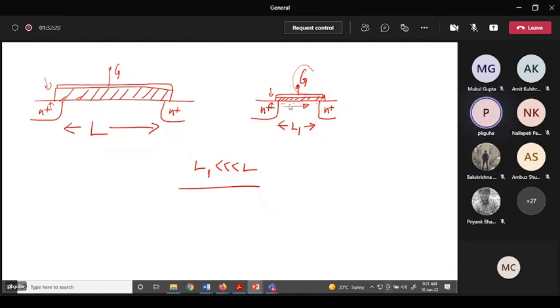Now, if you keep on reducing your Tox, it might happen one day that the oxide layer will be just a few atomic layers of SiO2. That can create problems, because the electrons might be able to pass through this gate oxide and create a lot of leakage current, and that may create a reliability issue for the device, because the thickness of the gate oxide will be very tiny, maybe just a few atomic layers, not easy to fabricate also. Even if you fabricate, that might create some reliability issue, right? So this was one of the major challenges.